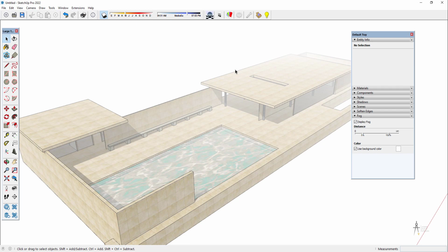Lines that have to do with architecture. Second step would be to export them or import them into SketchUp. Once you did that, we created our faces, remember creating the rectangle and intersecting it with the other rectangles. And after we did that, we rotated our sections so that we could use the height as a reference.